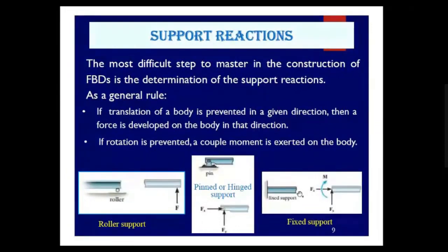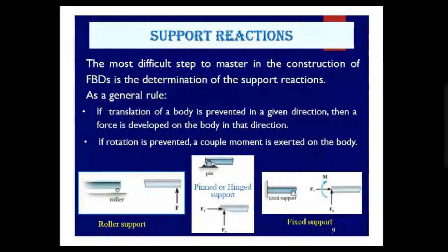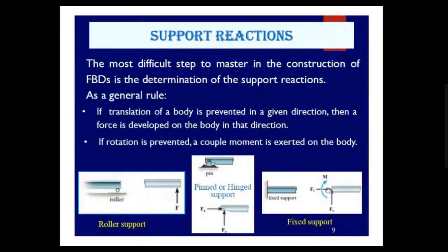It can also not allow the horizontal motion, so a horizontal force can be developed. It is also not allowing vertical motion, so this support can generate a vertical force as well. So this fixed support has the quality that it can generate three reactions: one couple moment, one horizontal force, and one vertical force.